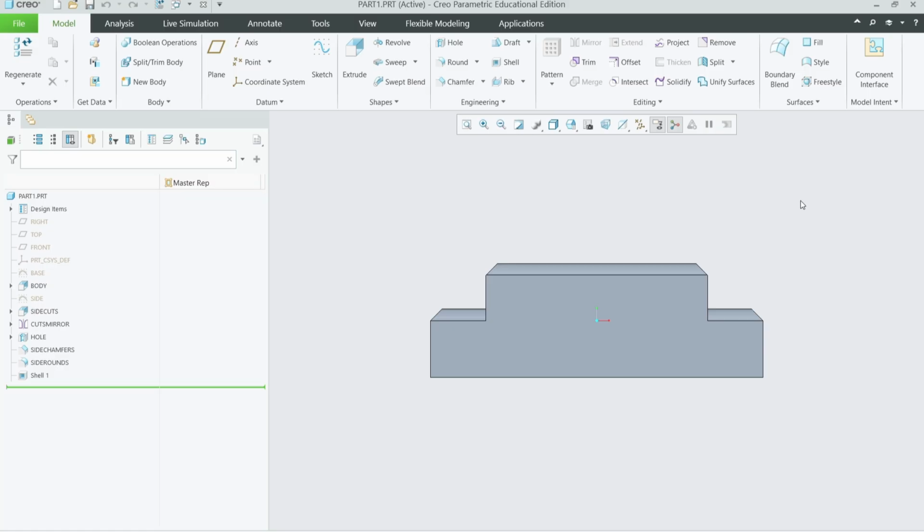This loads every feature, every detail, and every single piece of geometry. A SimpRep allows you to create lighter versions of the model or assembly, or different versions, which your computer can handle much faster, especially when panning, zooming, or rotating. This is also extremely helpful when you're designing more conceptual parts or just have different ideas for designing the part. You don't have to completely alter the part, or you don't even have to create a new part. You can just create a new SimpRep and model it using this tool.